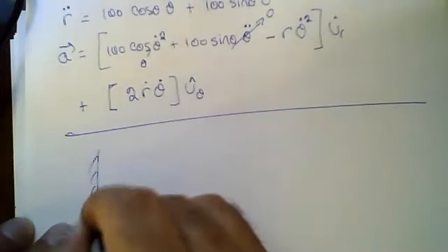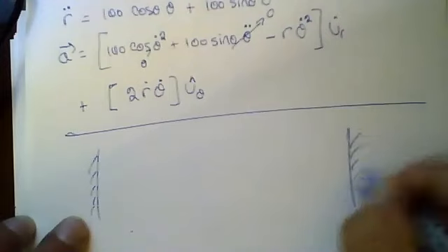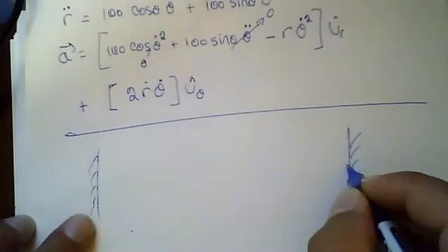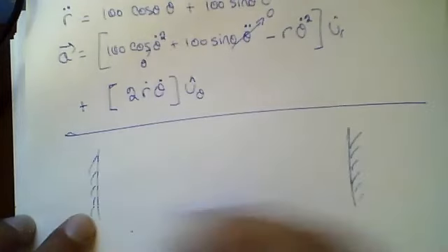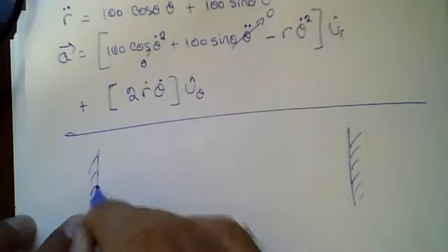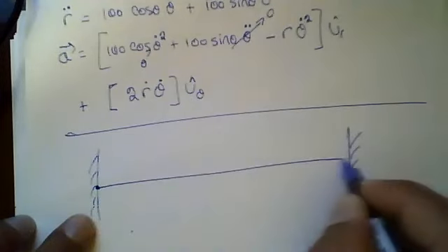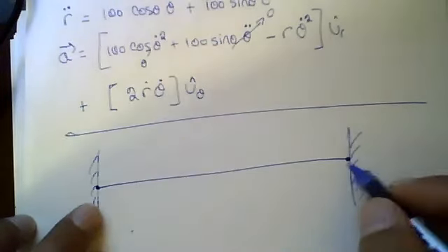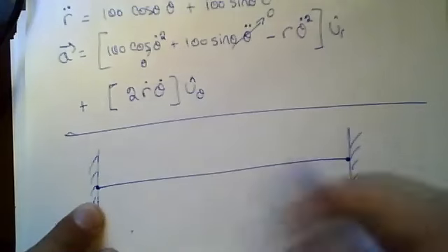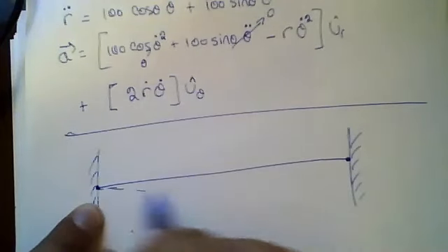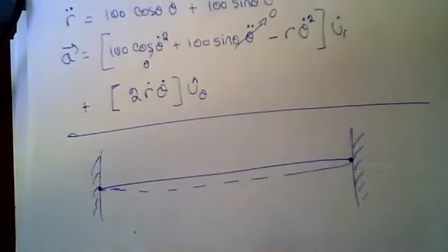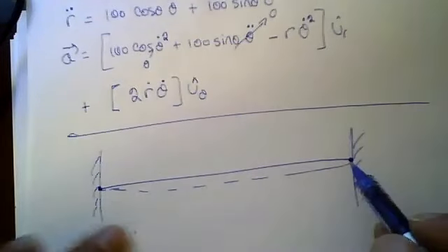If I have, let's say, a wall, and here another wall, right? And I want to have a cable, and I want to keep that cable in tension all the time, how can I do this? What would be the best way to basically keep that cable in tension? If I literally just bolt it here and then bolt it here, it's going to be very hard for me to create tension, right? And even if I actually have tension, as a result of creep, the tension will actually reduce at some point, right? Because as a result of heating, hot weather, cold weather, etc., the cable will basically creep.